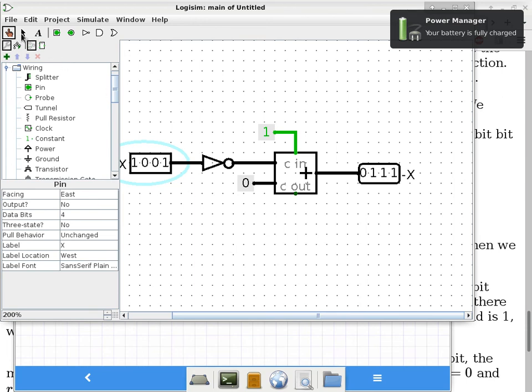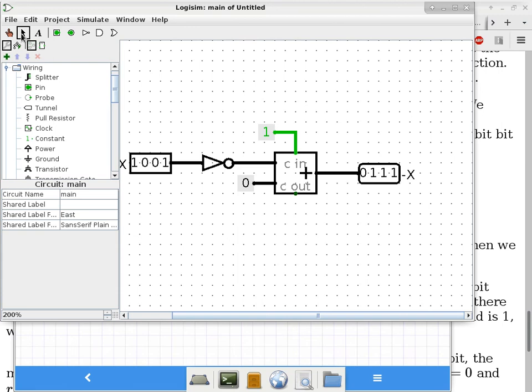Okay, so it spills out some bit patterns, and we are not even sure that 1, 0, 0, 1 is the binary representation of -7. How do we check it? Well, you guys know it already, especially if you're from the early lab. The poke tool, right? So you poke the wires. You poke this wire, it shows you what the bit pattern is, but it also shows you the assigned interpretation of those bits. So this is showing us that 1001 is a 4-bit number, has a signed interpretation of -7. It is representing -7. Yep.